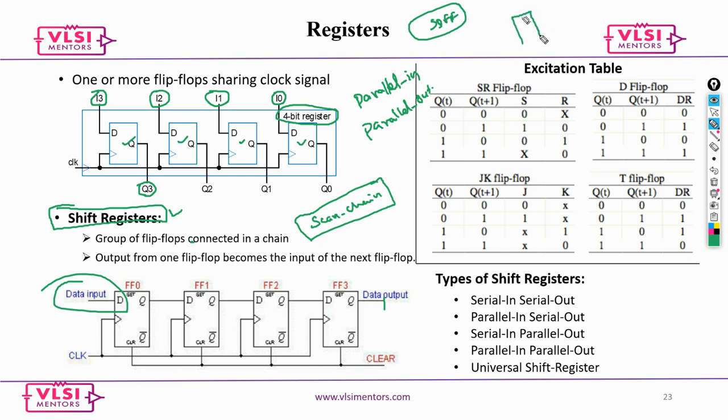In your normal flop, you will have the pins CK, D, Q, set, and reset. But in the SDFF, you will have D, SI, and something called SE, scan enable, then your clock, your reset, your Q, and your set.